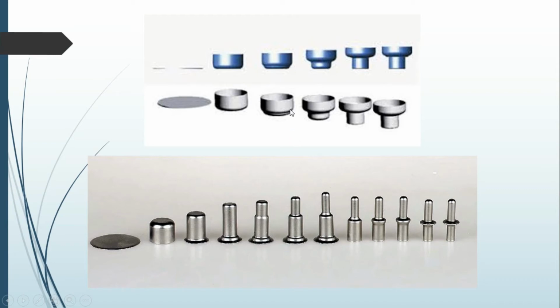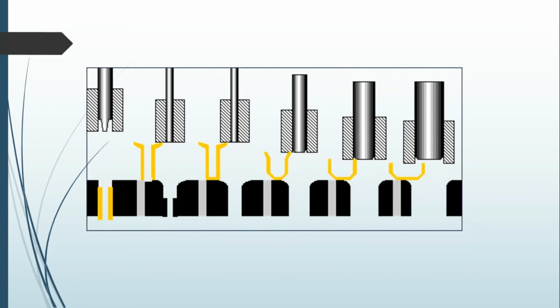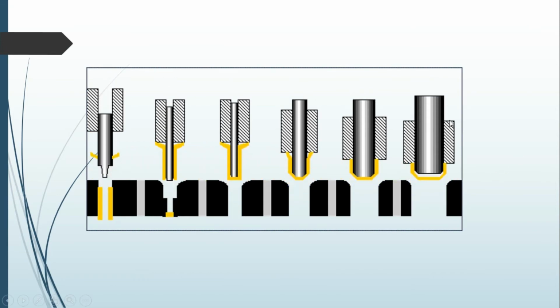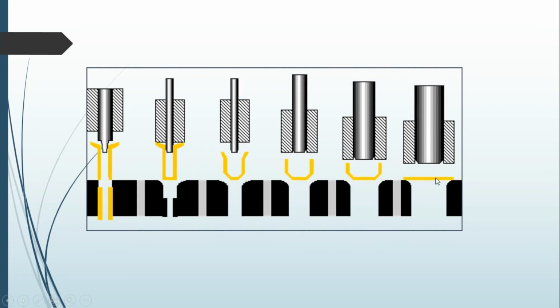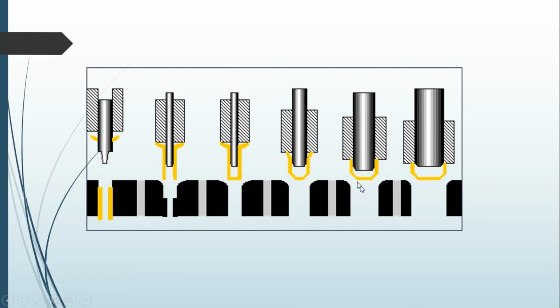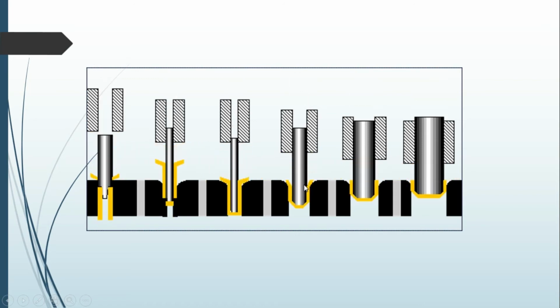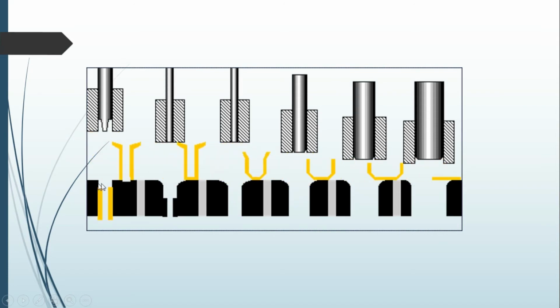Here also, the plate, bucket, mug or whatever, starts from this normal flat blank, and slowly it is deformed and its dimension is changed. And you can see this is how the product is going to happen. You have to read this diagram from right to left. This is the start. The initial blank is coming and the initial shape is made, then another deformation attempt, and we are going to get the clear-cut one, and finally the final product.